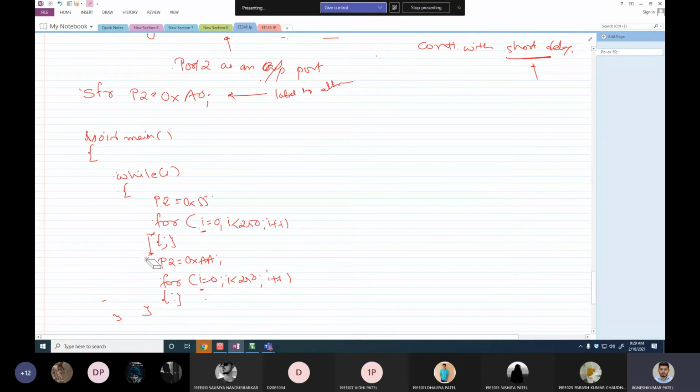So this is my program, but the thing remaining is that I should declare this variable i. We see that the number is 250, so I can use a signed or unsigned character. Obviously I'm going to use an unsigned character, because the sign is not at all important to me right now. So unsigned char i. This is the whole program.